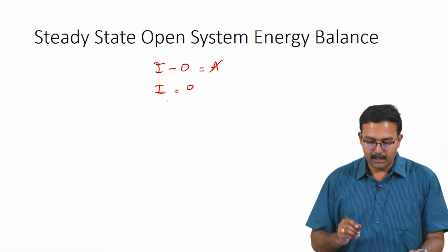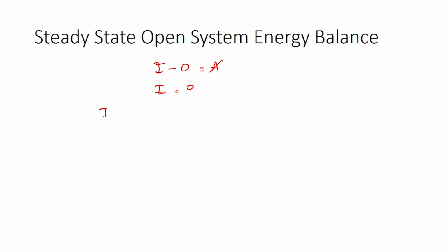So, let us start writing the balance equations for this. Energy which is fed to the system, the input, would be sigma of input of E j dot, where E is the total energy possessed by a component j, and the summation of all the energies of different components will give you the total energy of the input stream. In addition to this, you would also have Q dot, which is the heat which is supplied to the system. So, this would be a positive term.